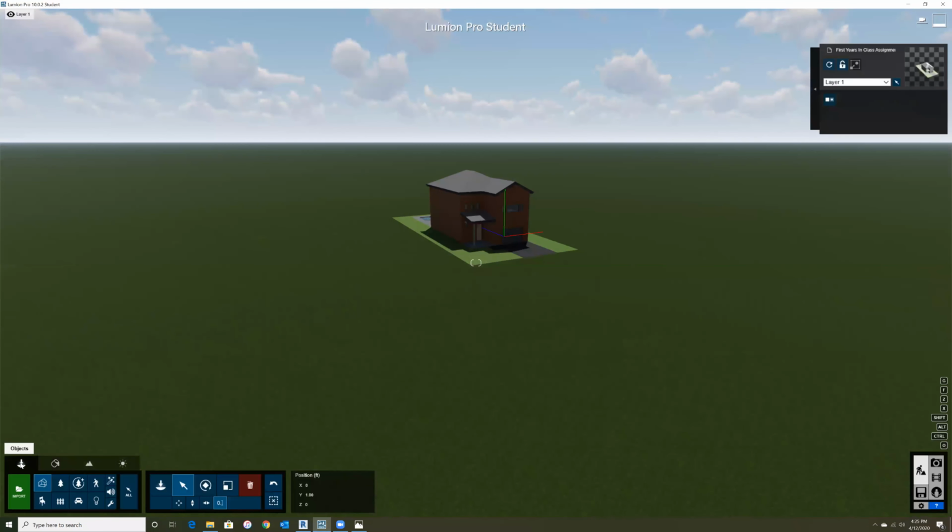If we go to objects, we're able to see the entire model that we've brought in with the name up here. And if there is ever some sort of issue, you can always re-import your model, which will pull it back in from Revit. Or if you change the file location, that's also a very handy thing to know.